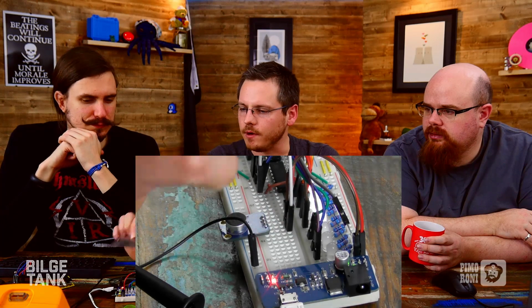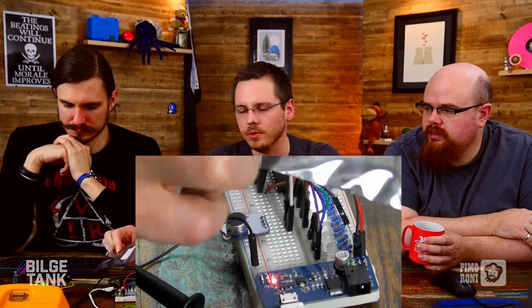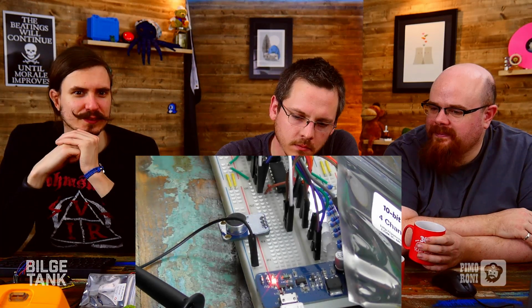Things like this are nice because I haven't used this one very often. I tend to use our breakout boards, but usually they'll carry on sampling in the background, so obviously you just go and talk to it when you want to take a reading out. Or some of them, I think, you can say start a reading now, and then you get a trigger or warning to say it's ready. We'll have a little interrupt pin that says conversion complete, conversion complete, and you drop in and go, oh, I have my data now.